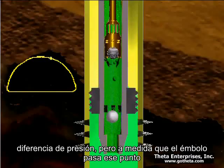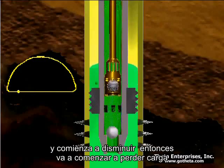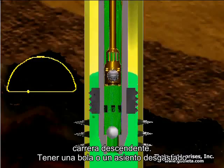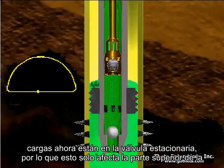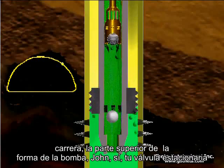But as the plunger goes past that point and starts to slow down, it's going to start losing load here. Of course, on the downstroke, having a worn ball or seat doesn't affect the loads because the loads are now on the standing valve. So this only affects the top of the stroke, the top of the pump shape.